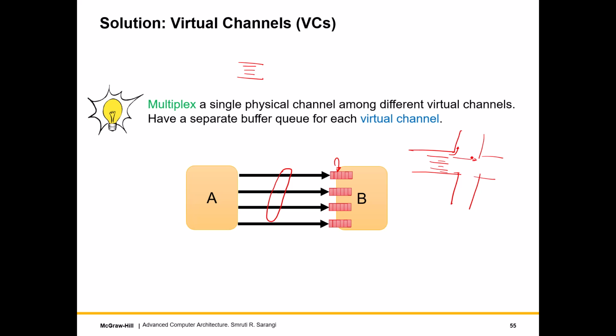So the same way that you divide a road into lanes, depending upon which part of the world you live in, if you have left side driving like in India, you would have a dedicated left turn lane, and that left turn lane traffic would not be blocking the traffic on the other lanes. Or if you have right side driving, you could have a dedicated right turn lane, and also a dedicated left turn lane where you also don't block the traffic that is going straight.